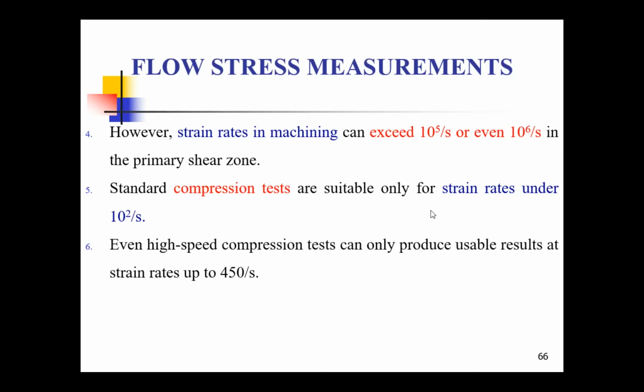with this flow stress measurement using compression test or tensile test, we cannot provide as accurate a material model into the package. So for this purpose, we should practically do some experiments in turning, and based upon that, the material model has to be developed.